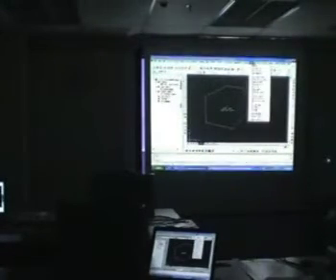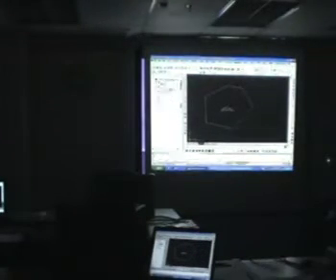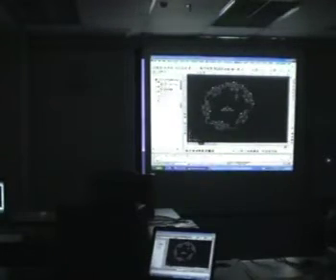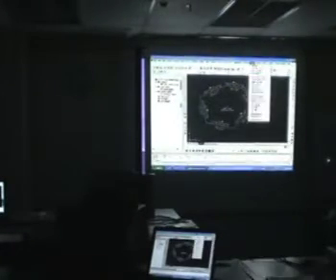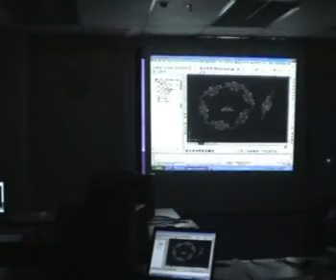For labels, we have two types of labels. One is a dynamic label, another is a static label. So I'll show you dynamic label first. So let's say I just pick this line. You can see how the text automatically appears. Now what's so dynamic about this is that if I reposition any of the points, let's say if I just move this here, you can see how the label automatically appears. Static is different in the sense that, say for example, I'll just draw a line here and use static label. If I reposition this, the label does not move. That's static label. So whether you want to use dynamic or static is completely up to you.